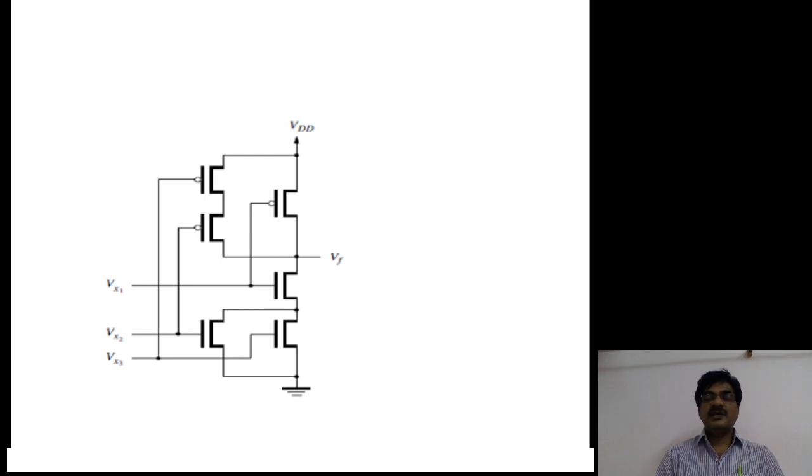How can you develop Boolean equation? With reference to pull down network, I am talking. If the connection is in series, the realizable term is product term. If the connection is in shunt, the realizable term is sum term. Okay? Right.